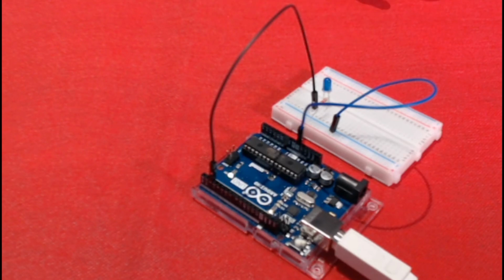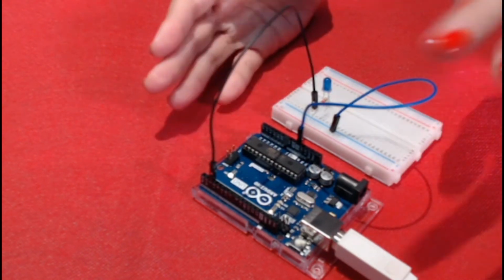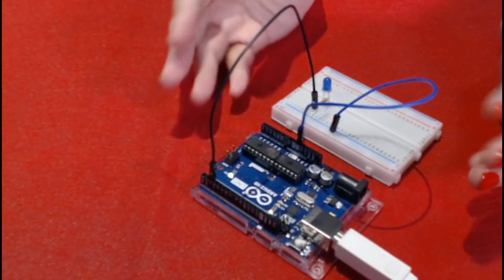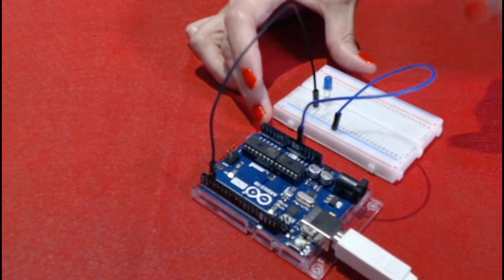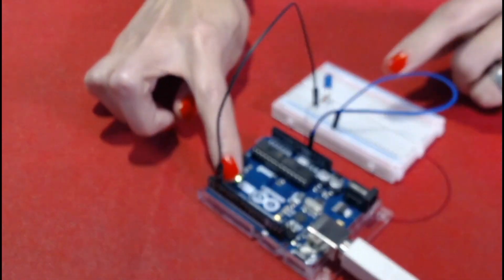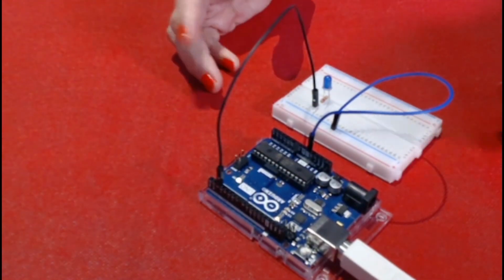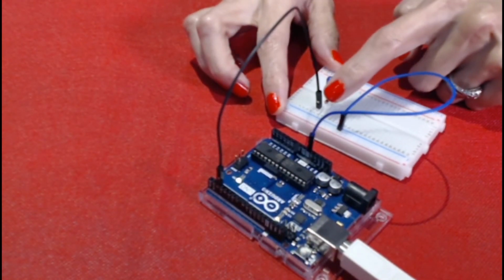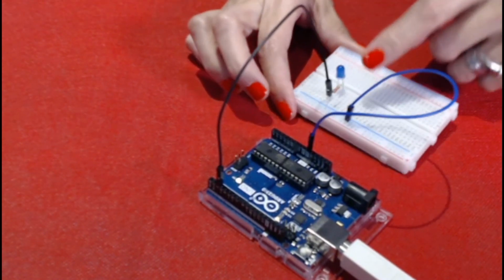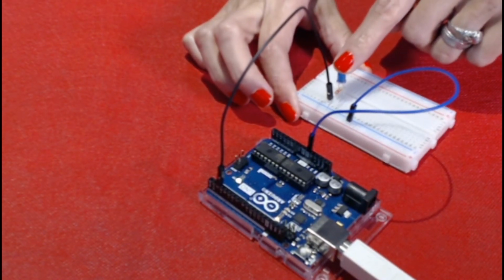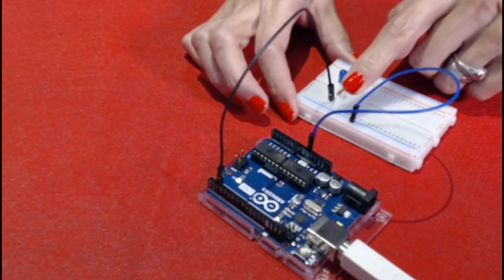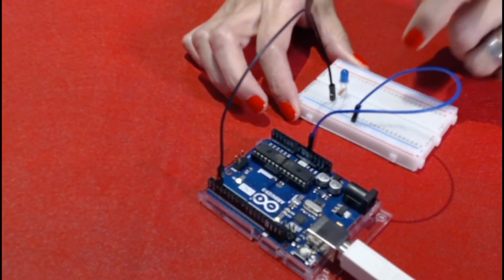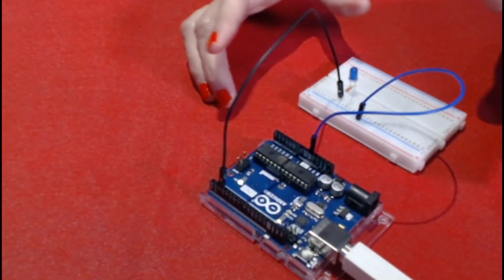In some cases, when the program is correct but the project is not working, we need to check the wiring. It can be a connection from the ground to our breadboard, or the connection to the digital side of our microcontroller. Sometimes the resistor is not in the ground place. And the last is the connection of the LED. Remember, the LED has polarity, so if the short leg is not connected to ground, the project is not going to work.